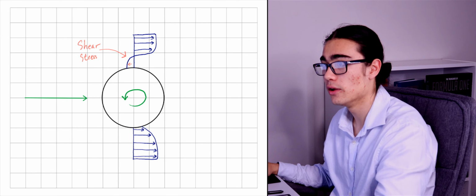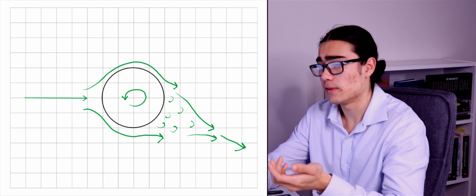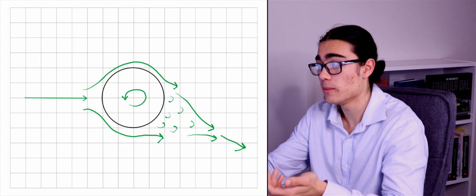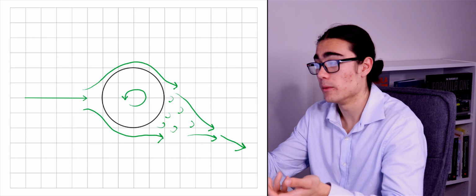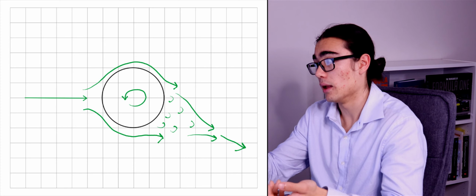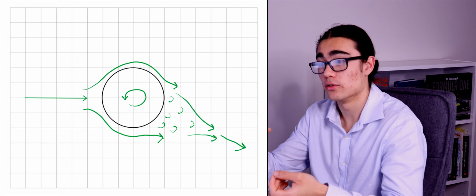And now if we've got turbulent flow, we're going to look like this. So our top side is actually staying attached longer than our bottom side, which is laminar, we're assuming, and the top side is turbulent. Turbulent, slightly thicker boundary layer, a bit more mixing, overcome the adverse pressure gradient a little bit better, and we've got a bit more attachment, higher curvature, and we'll extract a greater load.